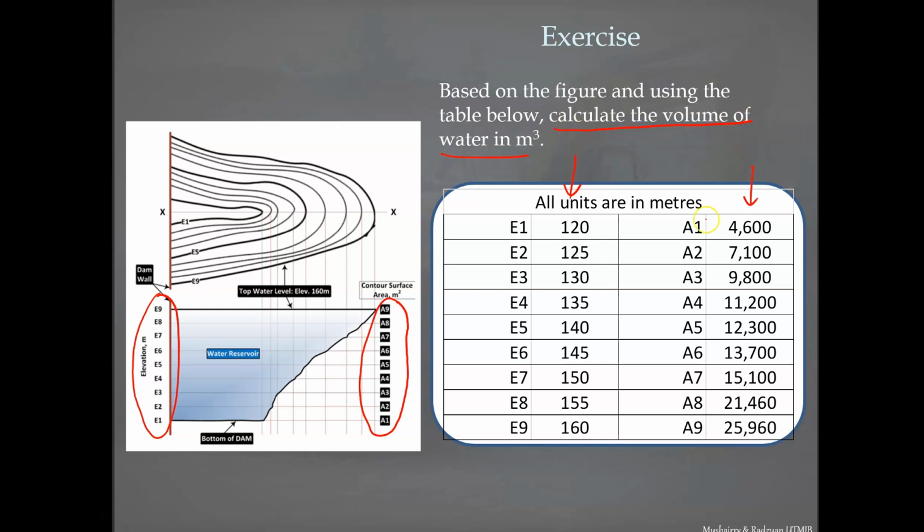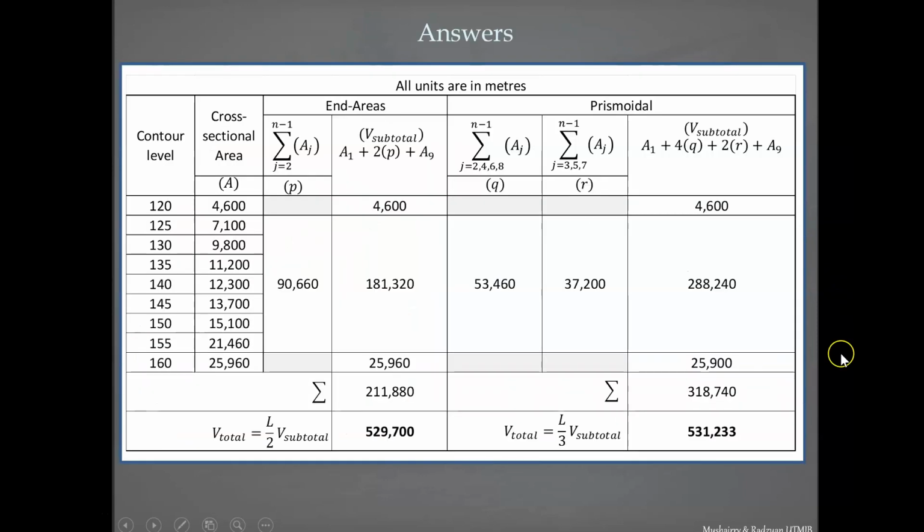By utilizing all the areas and all the elevations in here, the contour level and the area, we can calculate the volume. The next page shows the solution.